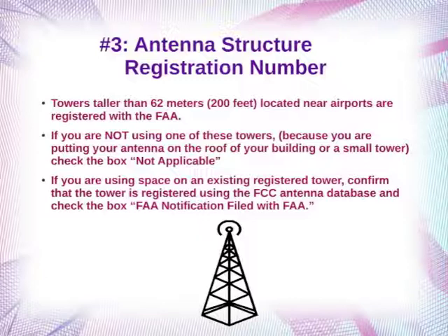By the way, somebody asked if the FCC will take the coordinates to the closest full second or fraction of a second. I believe that they will take it to a fraction of a second. I think I've used tenths successfully myself, and I suspect internally they don't really round it off at all. So you can put in whatever you've got. A tenth of a second, or a hundredth of a second, is about a foot. So you don't have to go overboard with it.